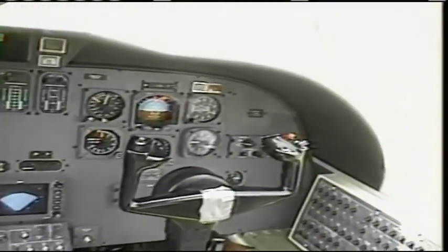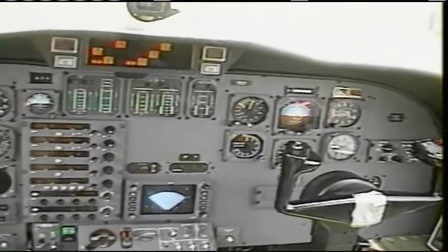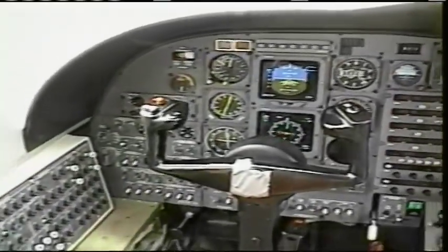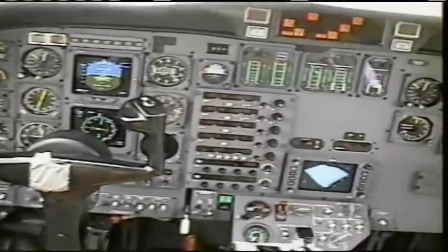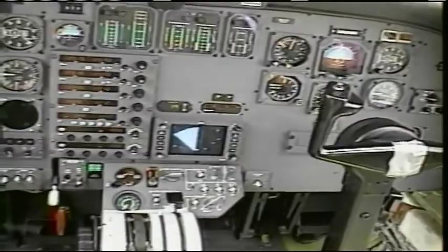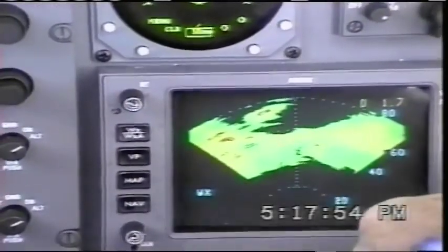As the radar sweeps, the blue-white pattern will grow outward. This progression allows pilots to gauge the status of the 60-second warm-up period. Just before this warm-up period is complete, the screen will turn black for a few seconds. Then the radar will begin transmitting and the screen will display radar returns. No radar transmissions occur until the warm-up period is complete.